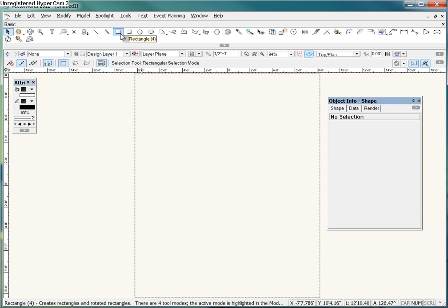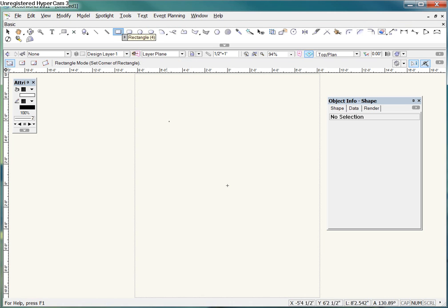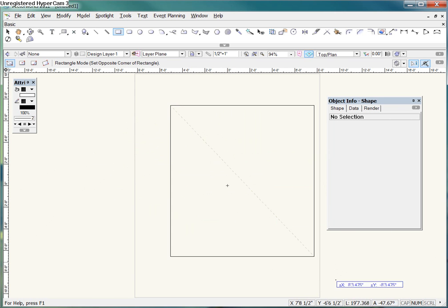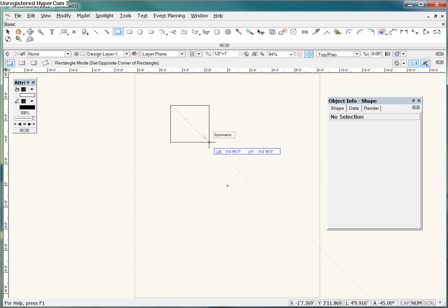Let's go ahead and use the rectangle tool right here to draw the outside of the door flat. So I'm going to select that and move somewhere in the middle of the drawing. It doesn't really matter where. I'm going to click once, and start moving to the right and down. And you'll notice as soon as I do that, I have this floating data bar. That's this blue box that's following my cursor around wherever it goes. It's mirroring a lot of the information that you see down here in the corner, but it's right there, sort of a heads-up display that's very useful.